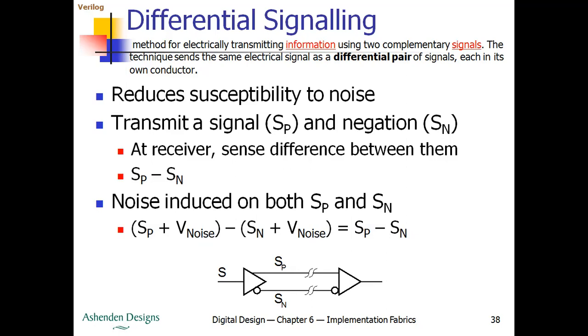For this common mode noise assumption, the differential signals must be routed along parallel paths of a PCB. You can see that the signals are inverses of each other, which means both signals change at the same time, so the crosstalk can also be cancelled out.